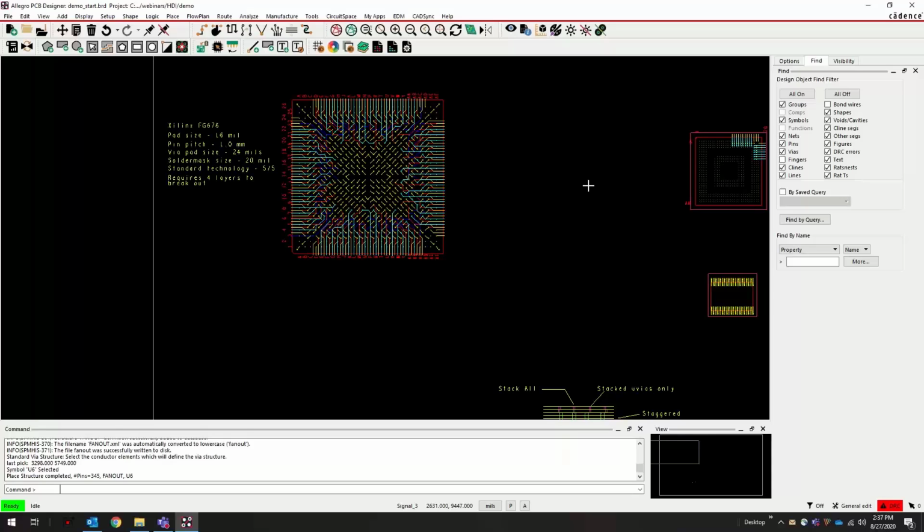then that's a lot of work that you've wasted. And so when you're doing an HDI design, just remember there are a lot of things to take into consideration. Using the micro-vias is going to give you more space in the design, but there's going to be an additional cost. So you have to weigh the cost versus the size of your design.